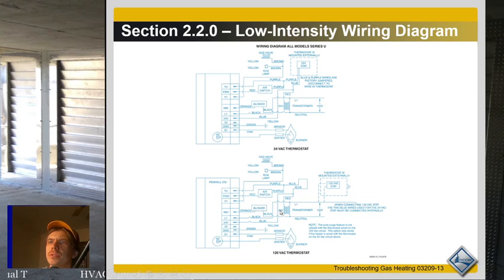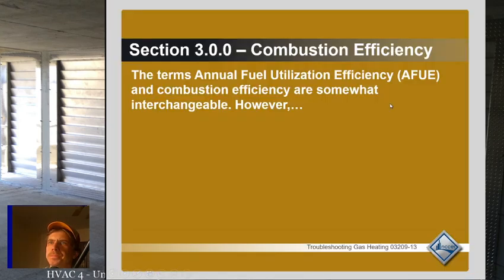They got an air switch on here, run lamp, gas valve. I mean, it's all just standard stuff. As a matter of fact, this looks like they're basically picturing a standard Honeywell spark ignition module. So these are usually universal, basically. So there's nothing really fancy about infrared heaters, except for the way that they operate. They tend to heat the surfaces rather than the actual air, right?